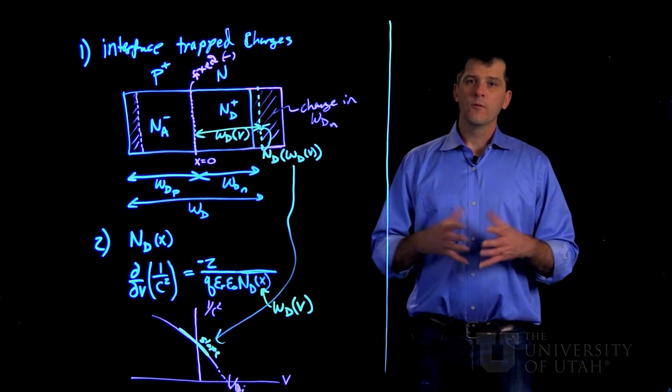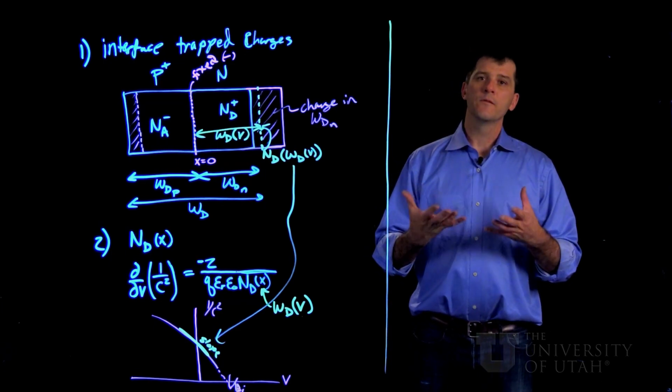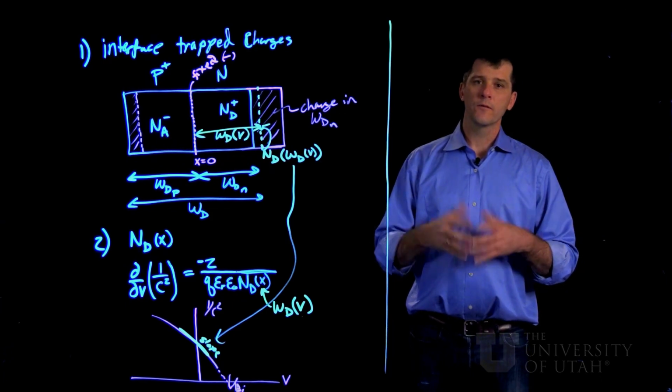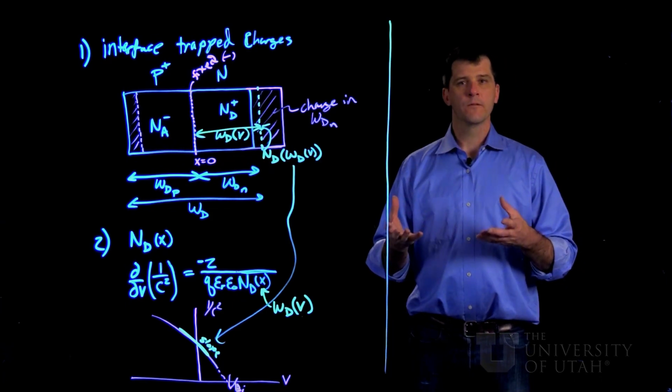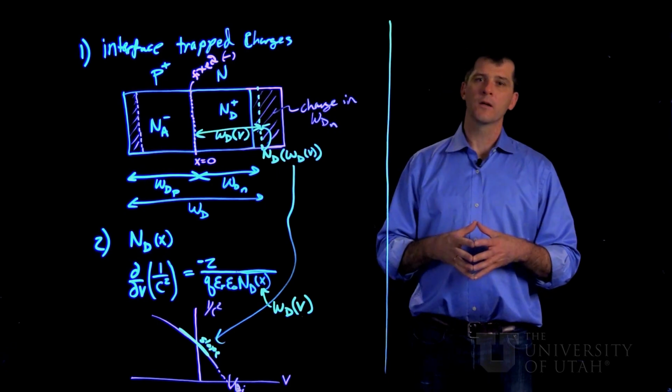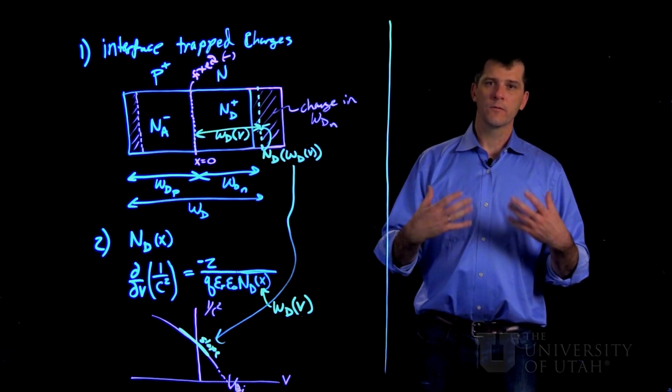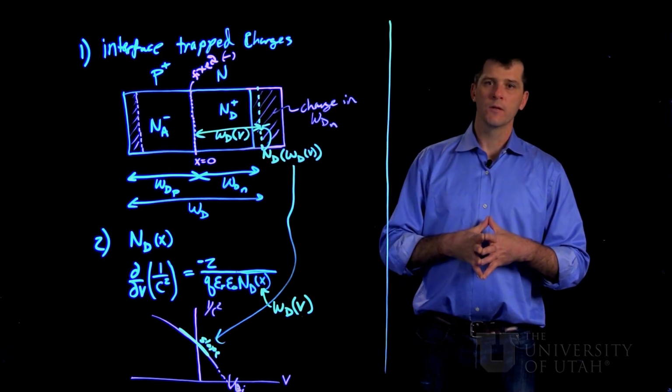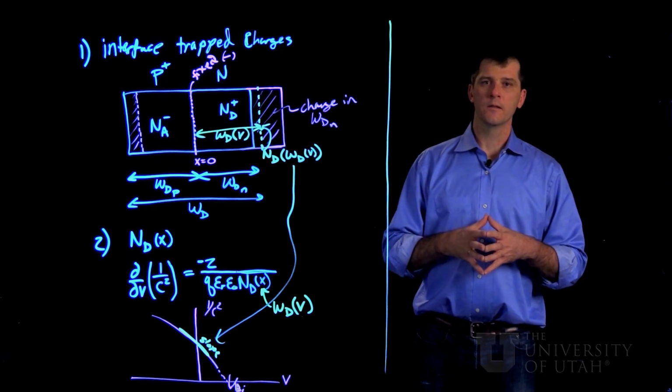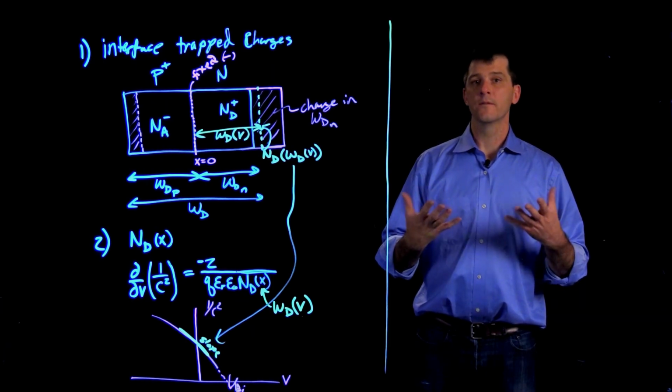So in the next sections, we'll talk about currents starting to flow in junctions. And first, we'll deal with breakdown and reverse bias, and then we'll talk about the currents which are introduced into the depletion width by minority carrier injection, leading to the ideal diode equation.